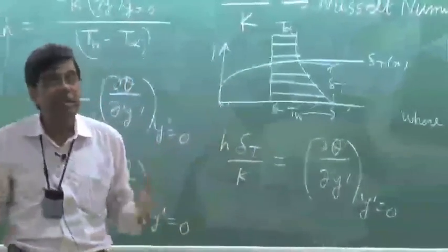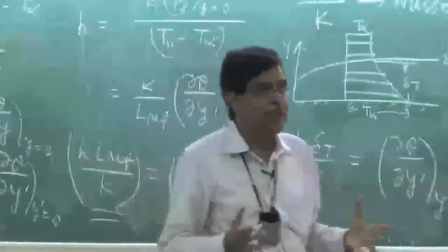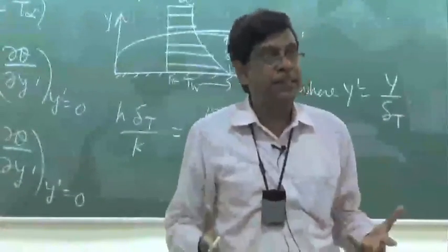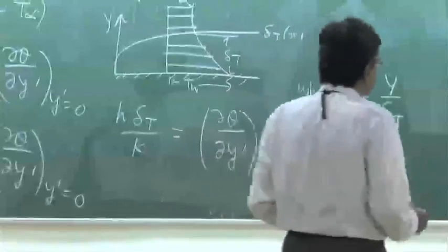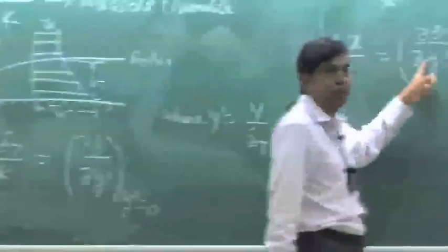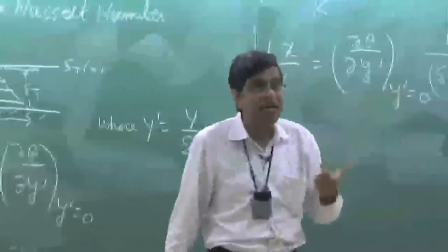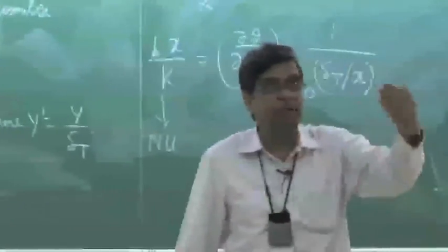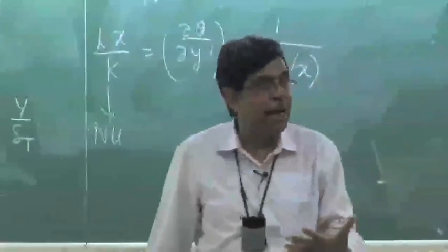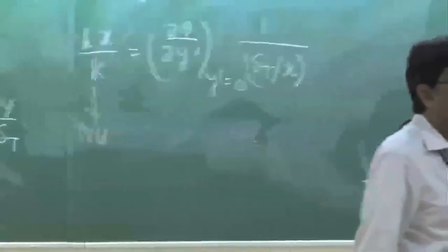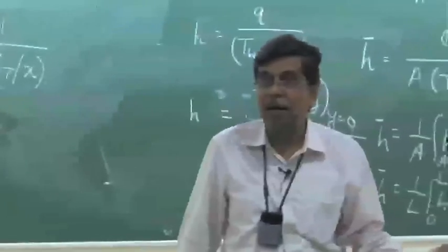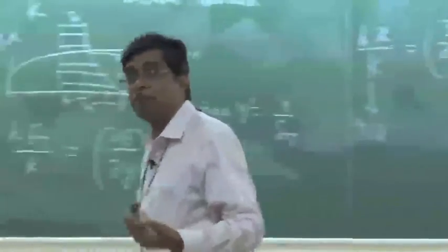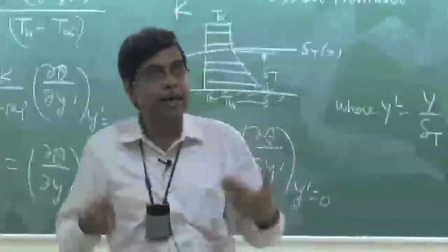And these two things are totally dependent on the fluid mechanics, that is the flow field and the temperature field. And this temperature field in turn depends upon the flow field. Earlier we have assumed certain things, that for a given Prandtl number, if we have delta as the hydrodynamic boundary layer, we have delta T as the thermal boundary layer, which is connected by a property known as Prandtl number. But how is it connected? How do I get the temperature field?